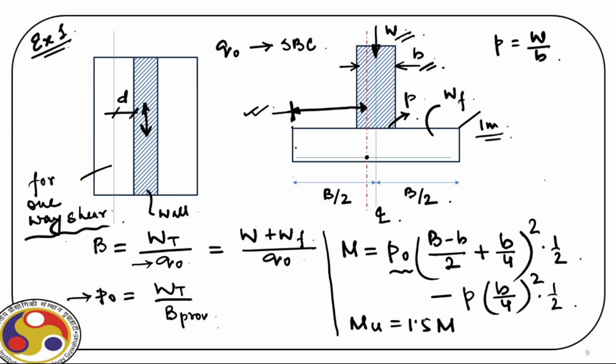From this, we have provided this is the length of the bar. So what we have to check is whether this length is sufficient. And for that, you all know the development length that we discussed earlier. So we have to provide sufficient length for anchorage. So this development length check is also required. From the dimension, we can quantify this length. We have to check the Ld.